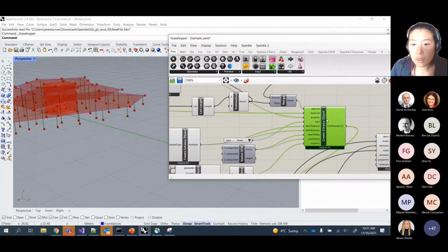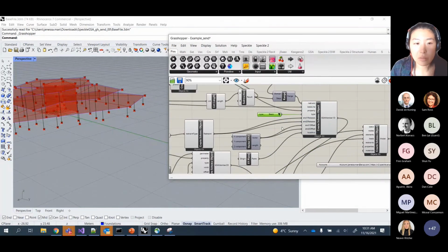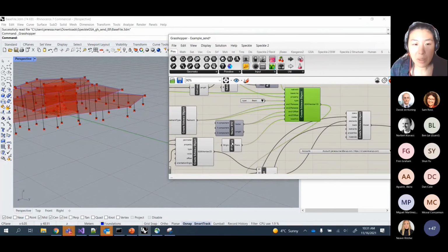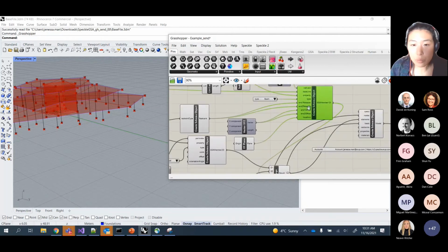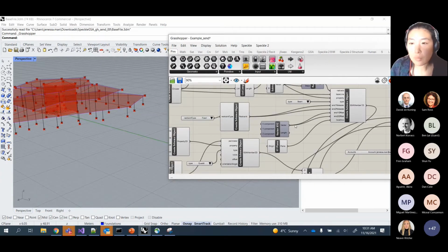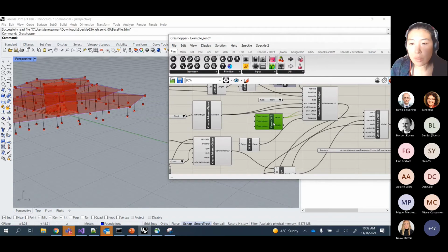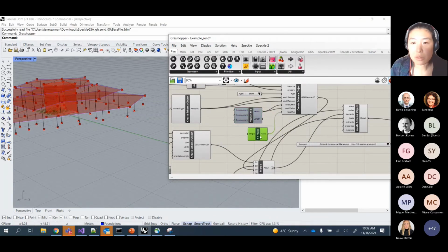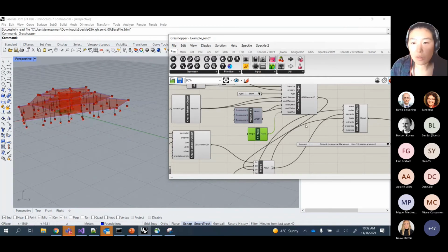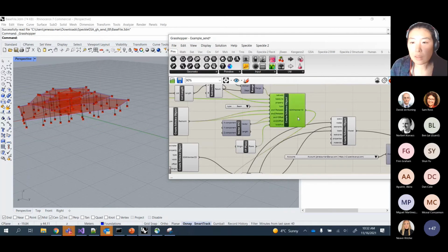Our property, this will be a beam type element. We're supplying some releases. So in this case, we'll just say that these are all fixed releases for now. At each end, we'll say that there are no offsets to the members either. And in terms of the local axis, we'll just use global XY plane axes to describe that member.